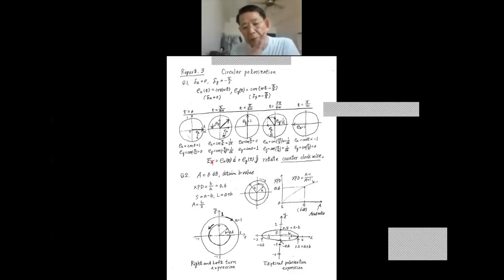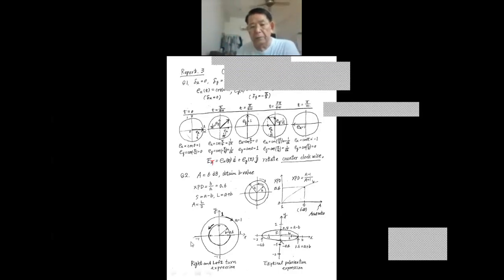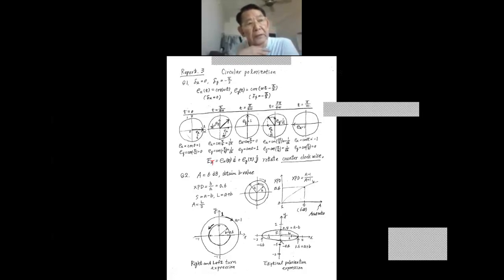If the dipole antenna is rotated in the plane, when the dipole antenna is vertical, this 0.4 value is obtained. And when the dipole is rotated to the horizontal direction, we obtain the 1.6 value. The elliptical locus is obtained when we use a receiving dipole antenna and rotate it. This is the result.